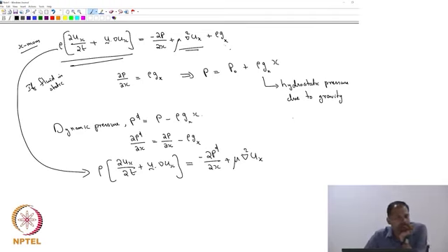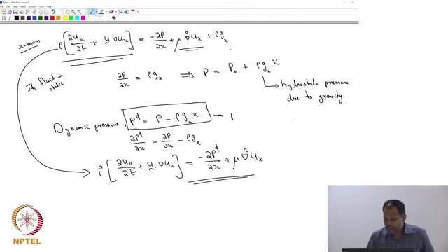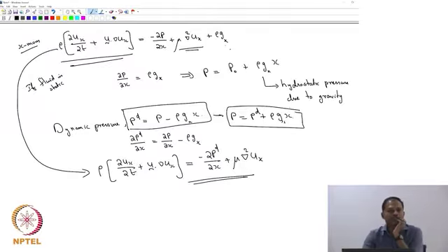Okay. So dynamic pressure essentially is defined in order to accommodate gravitational force, and this is the equation in fact that we solved throughout, right? So the pressure that we have really calculated even in presence of gravity was really the dynamic pressure. If you get dynamic pressure and if you want to talk about the total pressure, now you know the relation, you can use this relation and find that my total pressure is going to be nothing but P_D plus rho g_x times x. So that's a way to easily accommodate gravity without really caring about gravity. Is that clear?